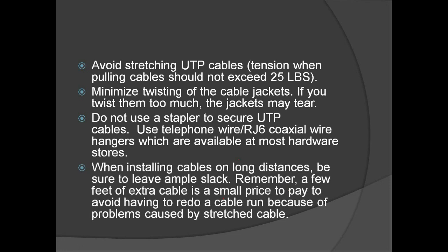Okay, when installing cables over long distances, be sure to leave ample slack. Remember, a few feet of extra cable is a small price to pay to avoid having to redo a cable run because of problems caused by stretched cable. So as much as possible, especially for long-distance installation of cables, make sure you add excess cable para in the event you need to troubleshoot, reconnect, or recrimp the cable, you still have access to work on. Mas mahirap na palitan mo yung buong kable.